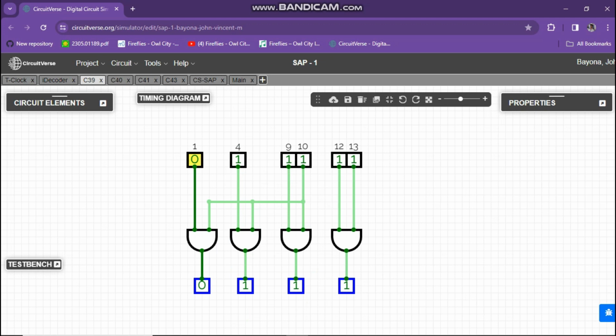In the addition mode, the adder-subtractor adds two binary numbers. Each bit of the binary numbers is added along with the carry from a previous lower-order bit. While in the subtraction mode, the adder-subtractor can perform binary subtraction. Subtraction is usually achieved by adding the 2's complement of the number to be subtracted.